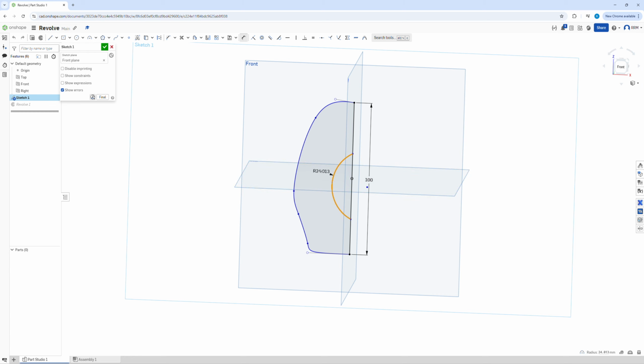The arc would be a little bit easier. I could have just made that, say, 25 millimeters, and I could make sure that this line from here to here is, say, 30 millimeters, and this line from here to here is, say, 20 millimeters. And we now have black constraints for there, like so. This, for our spline, I'll do that in another video.